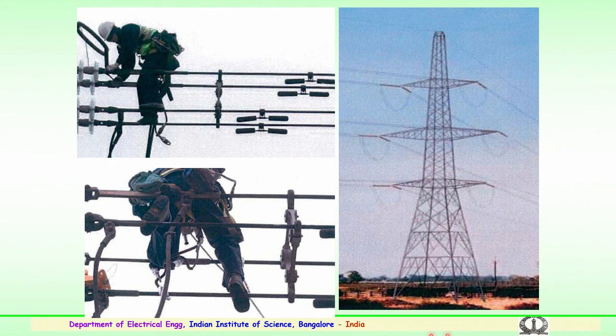So, here you can see various types of accessories which are being used for EHV or UHV transmission. This typical tower shows you the double circuit line here. You have 1, 2, 3, RYB is one circuit, and another is the second circuit. You have an insulator string. So, from the tower you have a jumper type of arrangement here. You have a twin type of arrangement where the clearances have to be maintained. Further to that, in the transmission conductors you see the vibration dampers which are fixed to each of the conductors.